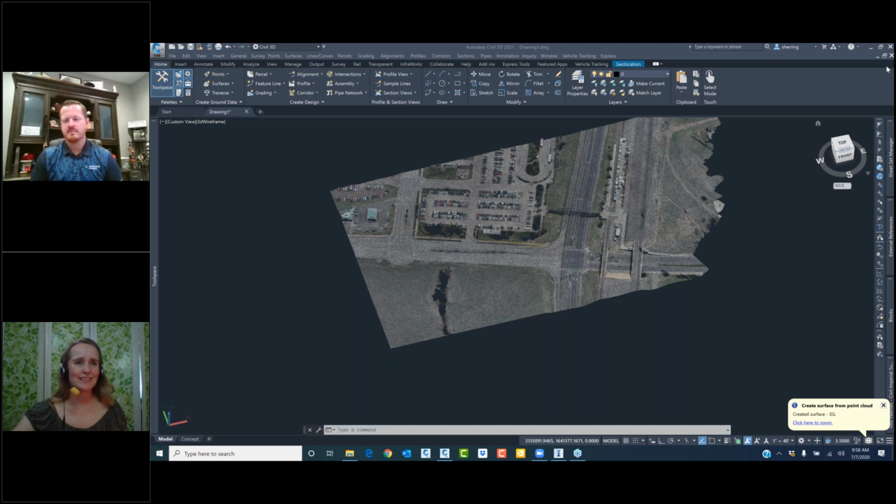Vemis asked, can you create or import point cloud regions in InfraWorks so that you can turn them on and off based on your proposal? No, that's a really good question. That's actually something I brought up because in Recap, you can create a region. For those that don't know, a region is, think of it as a layer. So you could create a region of trees or a region of buildings. And in Civil 3D, you can turn those on and off. In Revit, you can turn those on and off. In InfraWorks, you cannot yet.